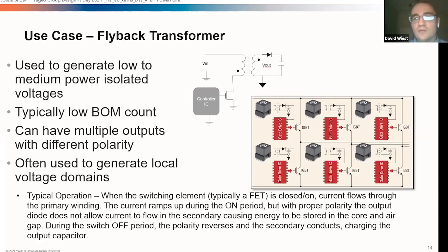One major benefit from the flyback is that you can have multiple secondary windings, or secondary outputs, isolated to their own grounds, simply by adding an additional winding on the secondary. So an easy way to generate additional power supplies. These are also usually fairly tightly regulated. As an example, you may find flyback transformers used to generate local reference or local power supplies for IGBT gate drives used in motor supplies.